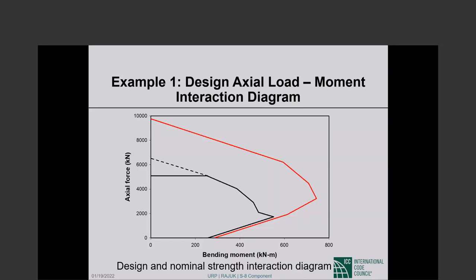Remaining column capacity would make sense if there is just spalling. You probably will forget about the covered concrete. Theoretically, you should figure out the strength of the reinforcement in place by taking some coupons or something.